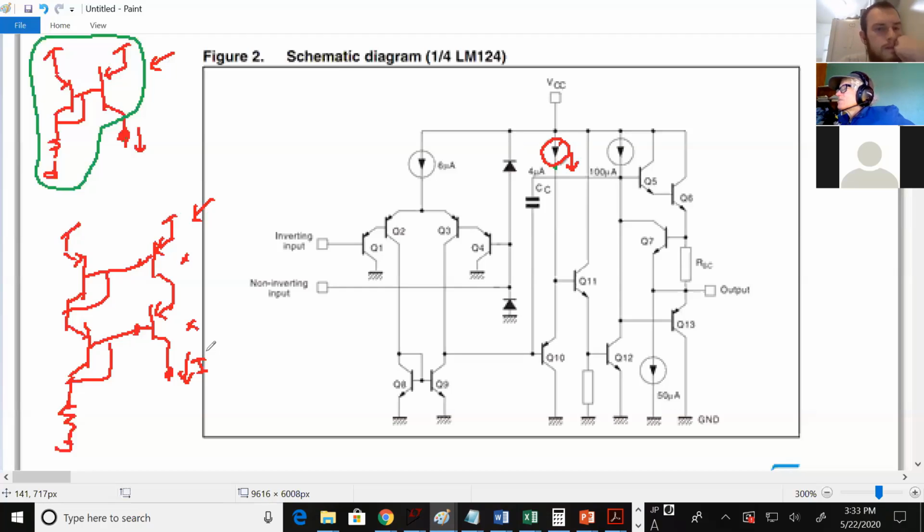If RO is 100K, it's pretty darn good. If you need a giga ohm, then cascoding is super great, but RO might be just fine. In this case, you'll have a gain just slightly less than 1.